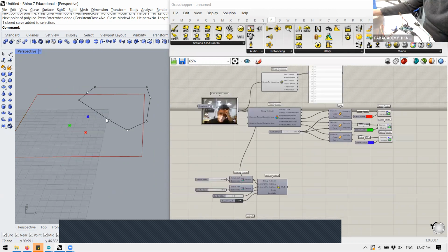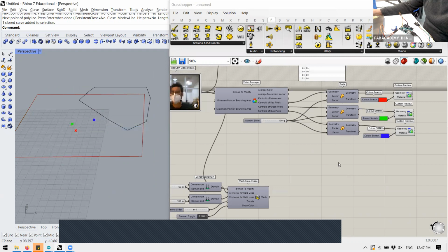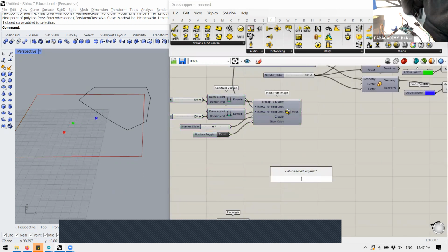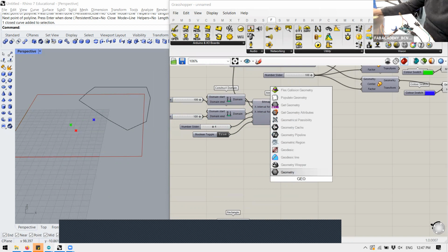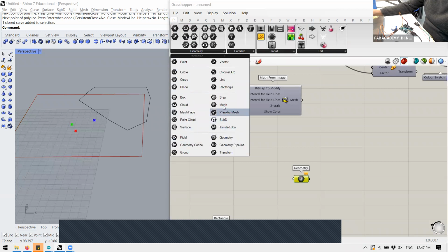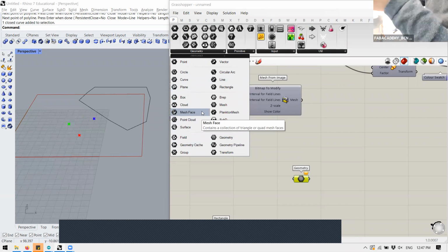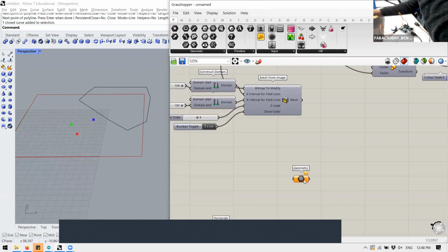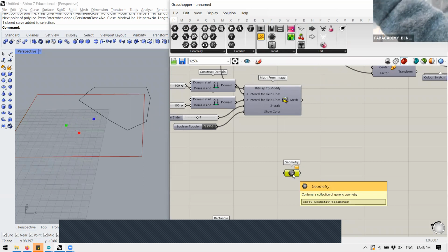Do you remember how we put reference lines into Grasshopper? We use components like geometry, the basic ones that are in Params, Geometry. The black hexagons are empty components we can use to connect things inside Grasshopper or reference ones. We could use curve, yes. I usually use geometry, which is a general all-worker. It's not specifying anything. It's good and bad at the same time, because you don't know visually what you have inside, but you are able to connect whatever.